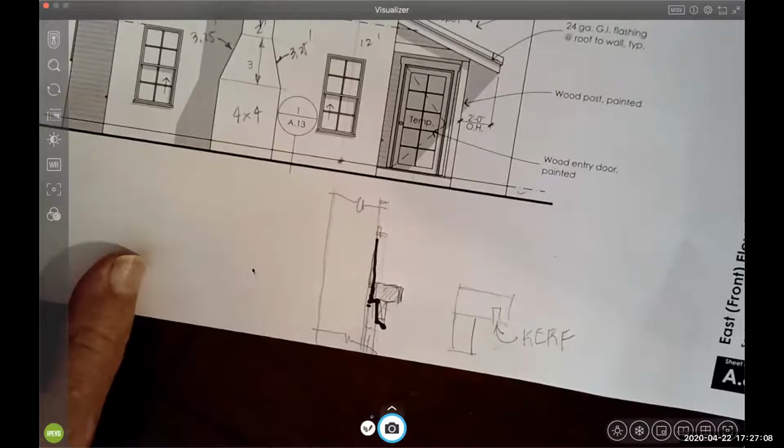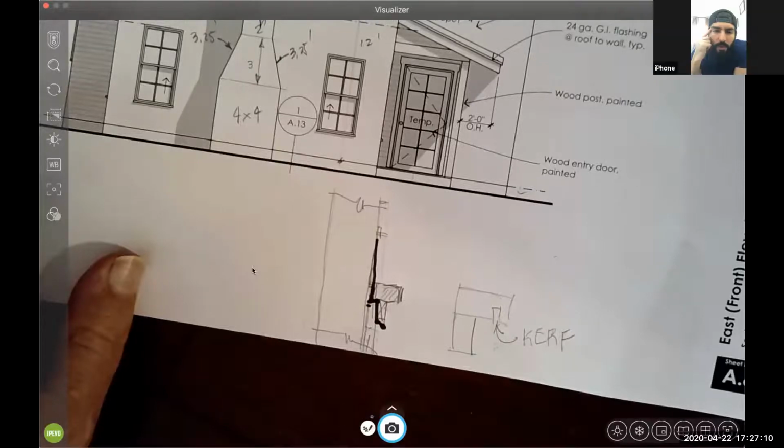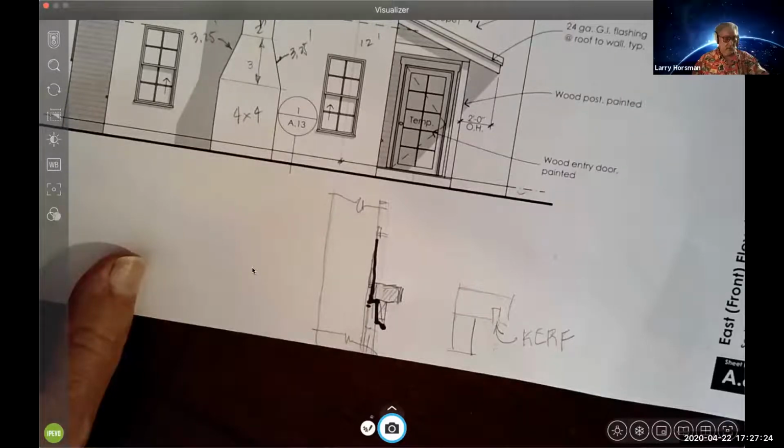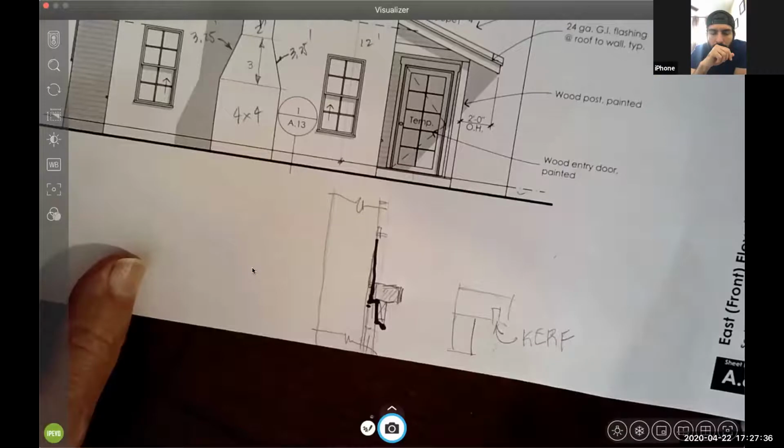Larry, quick question. Last time we did the stucco in the building over here for the city, there is a wire mesh underneath the stucco where they hang up the paper. Yeah. At the end of it, there is a piece of metal to cut each 10 feet. Yeah, there's a drip screed at the bottom. So at the bottom, we have a weep screed or a drip screed that fits behind the stucco finish, right?